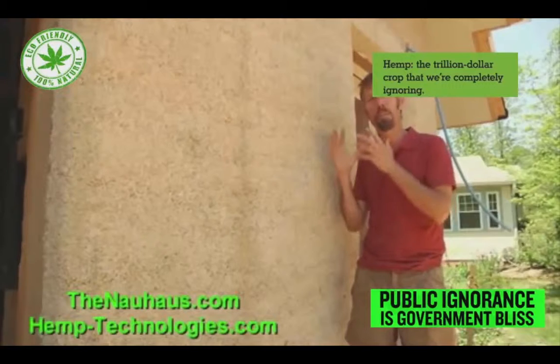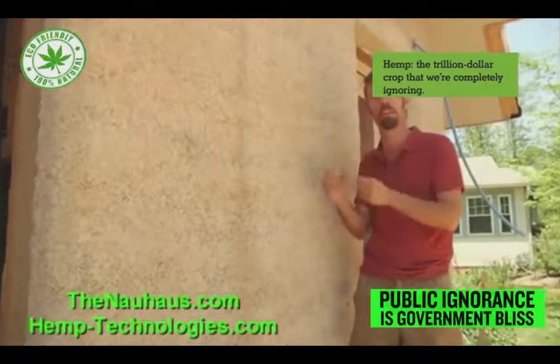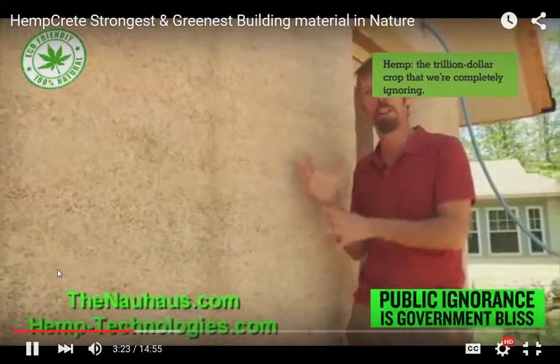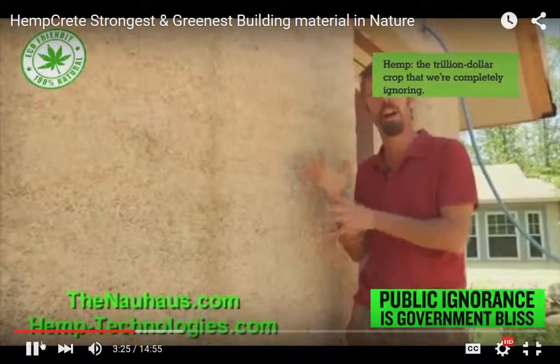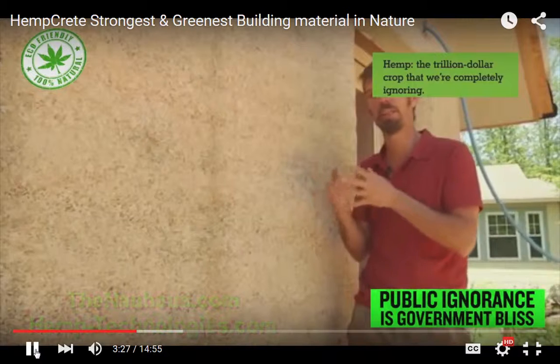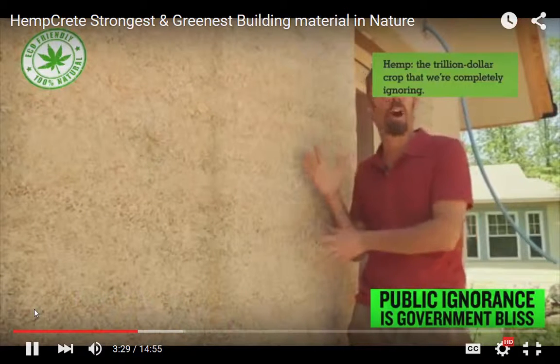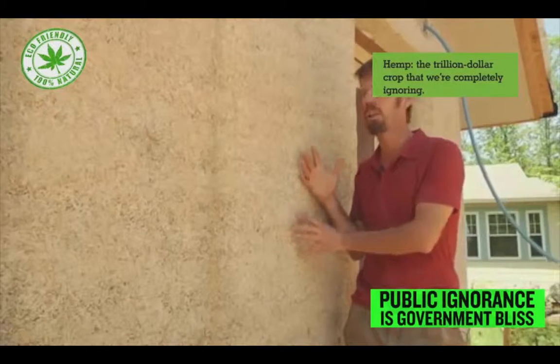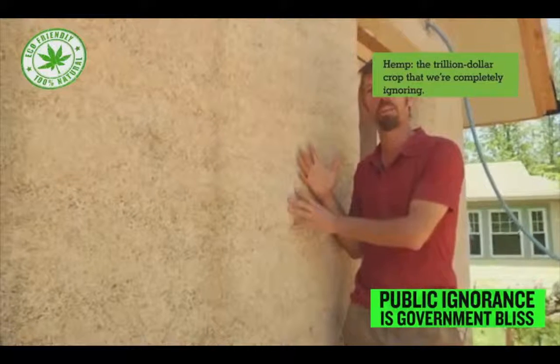I think hemp's an important thing to push because it's food, fiber, building material. But really, I'm choosing this material because it's the best in terms of building science. And why is that true? First of all, because this is what's often called a breathable wall system. And I don't mean breathable for air. We're actually building an airtight wall, but it's breathable for water. And why is that an advantage?